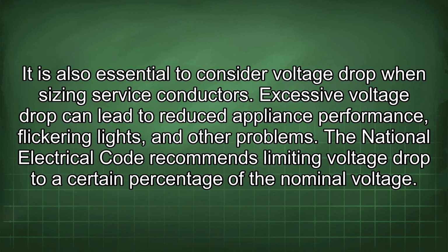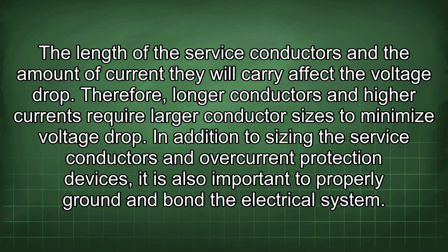It is also essential to consider voltage drop when sizing service conductors. Excessive voltage drop can lead to reduced appliance performance, flickering lights, and other problems. The National Electrical Code recommends limiting voltage drop to a certain percentage of the nominal voltage. The length of the service conductors and the amount of current they will carry affect the voltage drop. Therefore, longer conductors and higher currents require larger conductor sizes to minimize voltage drop.